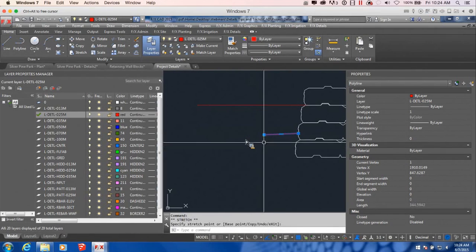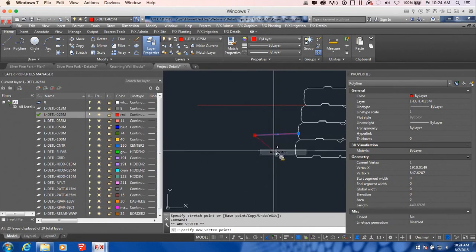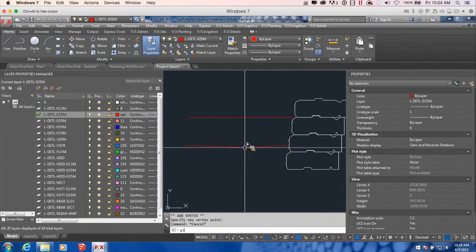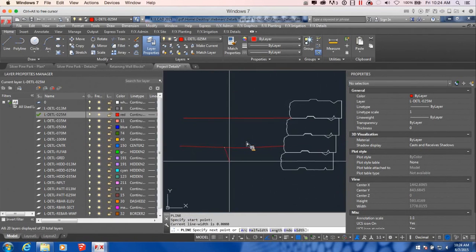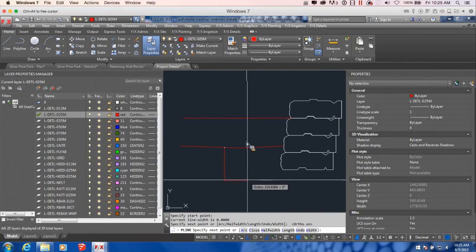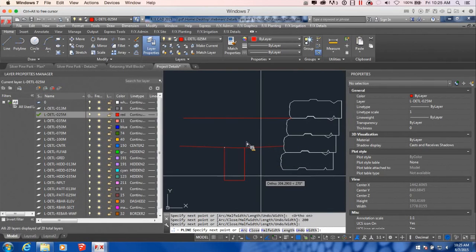Slope that just a little bit, about a foot away. Great, and add a vertex and slope that back up. And then just draw my drainage. I'm being a little bit loose in this one just because it's a webinar, so we'll pull in my drainage. Obviously you'll be a little bit more precise. My drain pipe's about 150, so 200 wide drainage trench should be good for this.